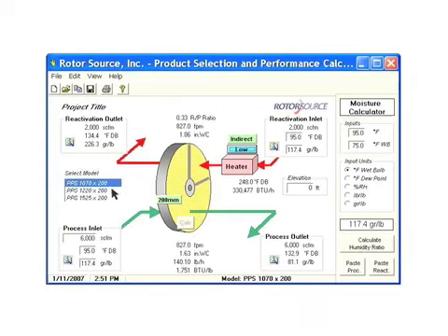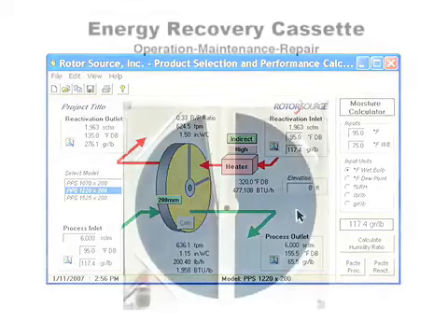You can also look at the next larger size wheel, as with the Energy Recovery program, to then look at the different effects. In the event that a user is using a direct-fired natural gas furnace, use of the Indirect button will add the moisture created by combustion such that it is represented in the exhaust air. Again, this program selects different models which are then used with our drawings and our data sheets to give the best representation of submittal for selection, and both programs include an elevation input for different heights of elevation.